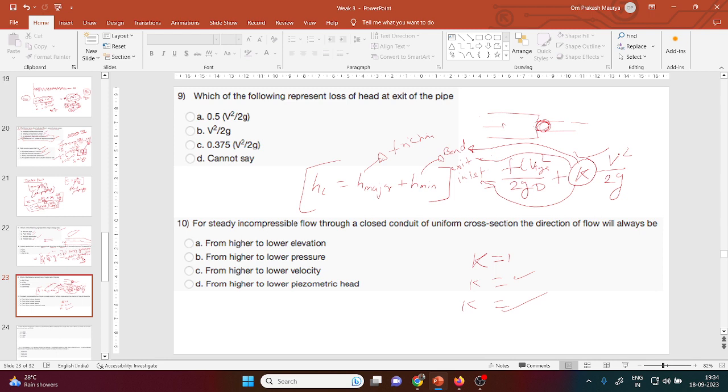What are you telling, Francis, tell again. Actually, we name some constant terms, like notch sensitivity factor, coefficient of discharge, like that. Is there any name for that K? Yes, it is like that. This constant we will multiply. Let's say I have an example for pipe exit. For pipe exit, K is equal to alpha. You already know what alpha is, the kinetic energy correction factor.